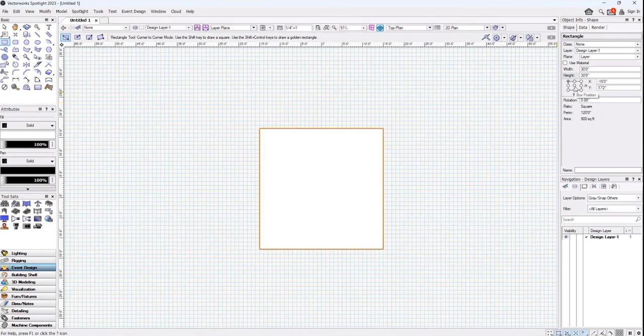This next layer is its position on the actual grid itself. And because this is going to be a room in the future, we want to make it dead center. You'll see why here in a second. So each of these correlates to a position in the 3D world. If this is lit up, it's going to move this corner to these coordinates here, where you can see it's at negative 15 and 17 already. If we go to center, we're going to make it 0, 0. So what this does is it actually centers the room for us and gives us these cool little hash marks that also correlate to the measurements up top, which allows us to align things a lot easier.